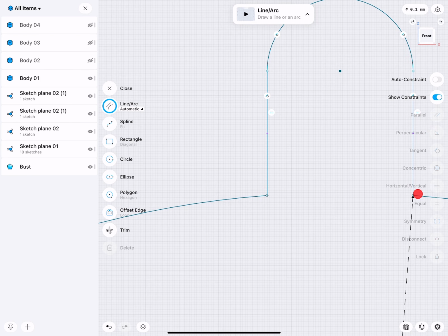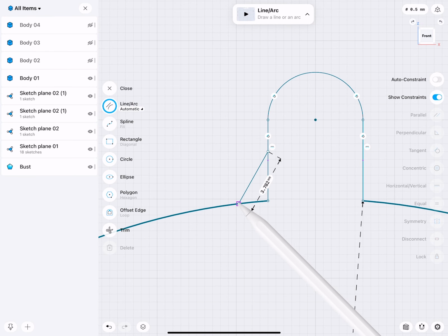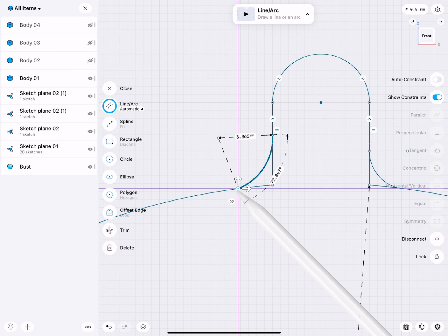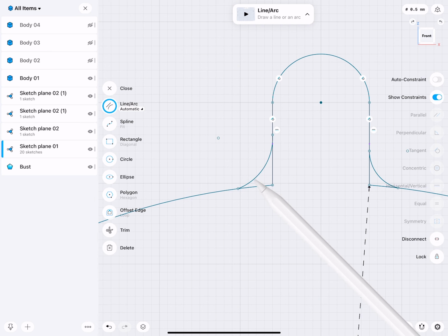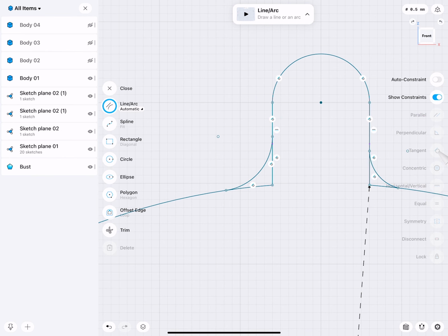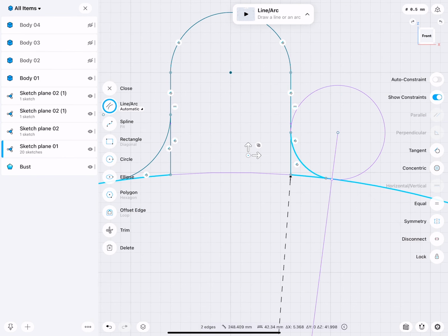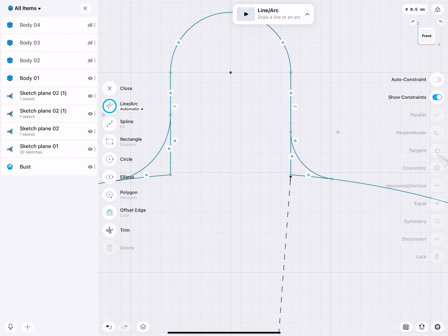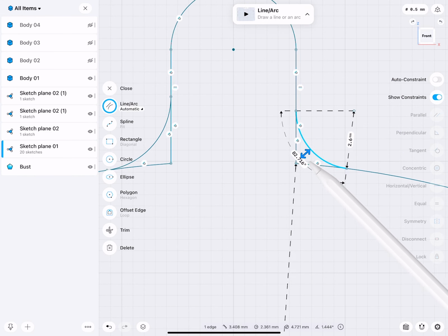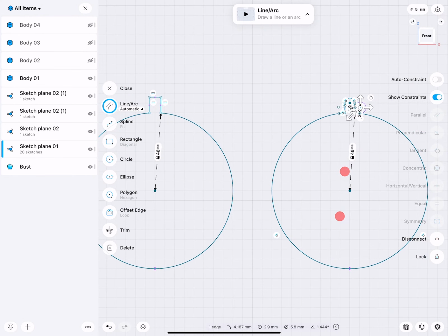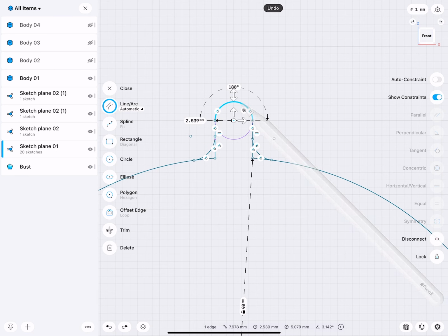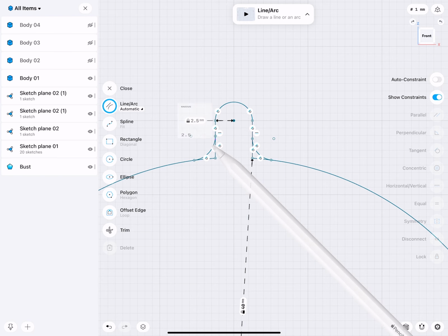So how do we now create arcs in there? That's actually really easy. We draw arcs, and with arcs I actually meant fillets. Very good. There. Now tangent, tangent. And because I reapplied all the tangency and dimensions and vertical horizontal constraints before, the rest of my sketch does not update in ways I don't want. Actually, here it does a little bit. So one thing I did not do, let's see. Yeah, this radius here I did not specify, 2.5.